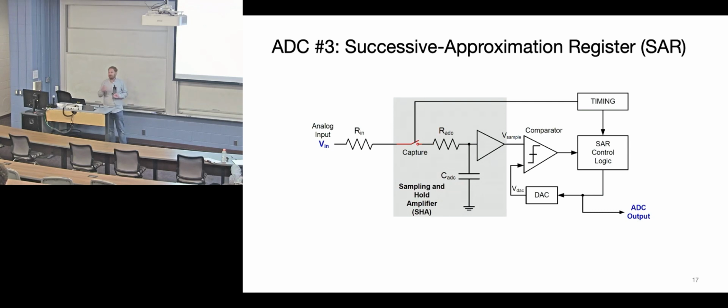For the slope integrator, what's one pro and one con? They don't take up the space at all. They scale really well. Yeah. Comparators consume a lot of power. You only have one comparator. You need some fancy analog current source. That's fine. Those things are all relatively small. So yeah, it's small. What's another good thing about it?